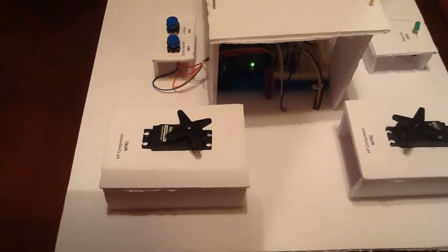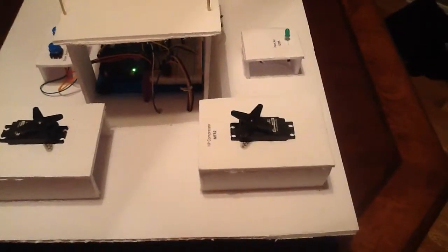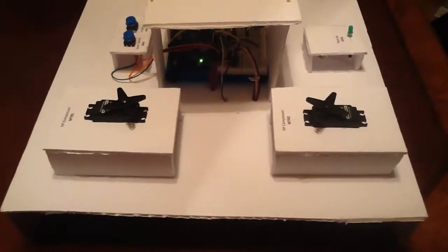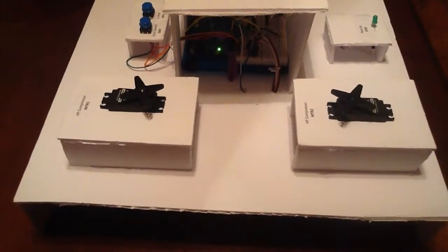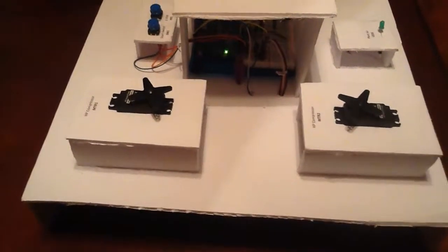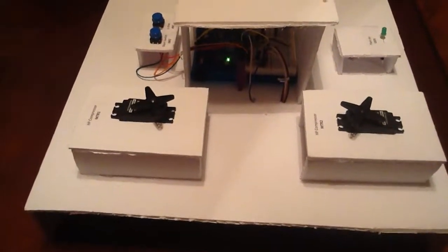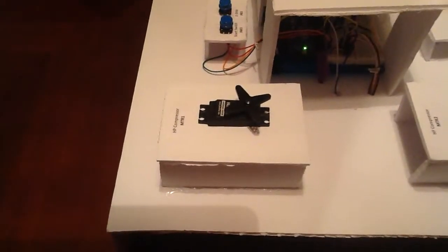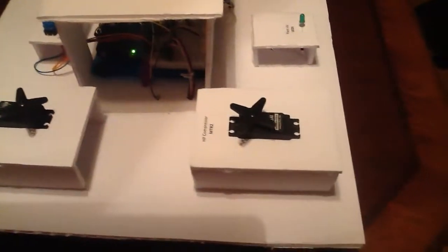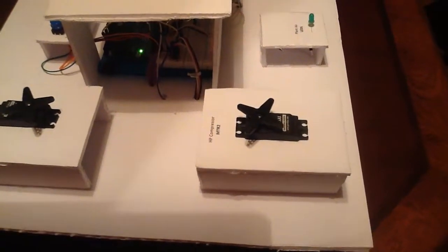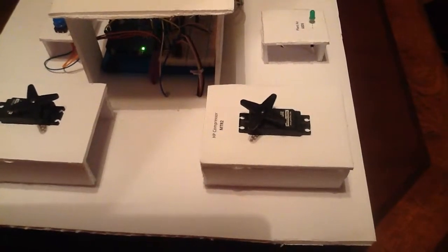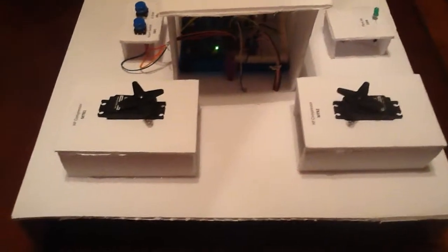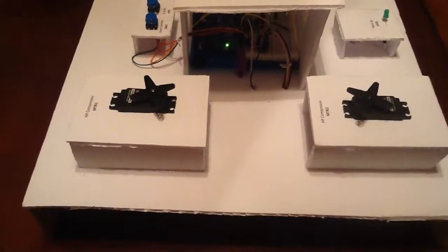Over here, we've got the 2 servo motors. One of the servo motors is motor 1 for the high pressure compressor, and the other one is motor 2. To show a drastic change in the amount of air being produced, these servos have been programmed to be either idle at 0%, or they will run in one direction for, in this case, this one will be at 70%. In this case, this one will be at 50%, because that is the actual reality of the motors on site at the plant. And then both of the motors will switch direction when each of them respectively is running at 100%.